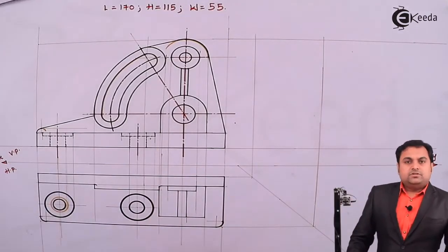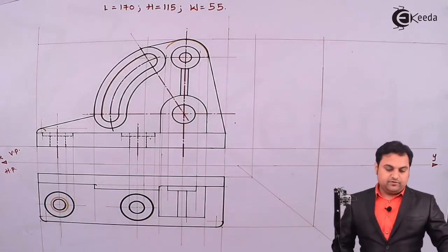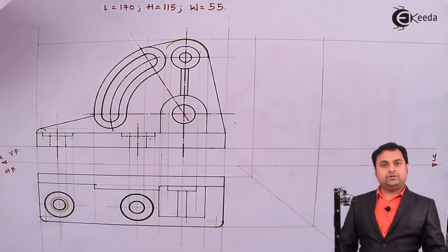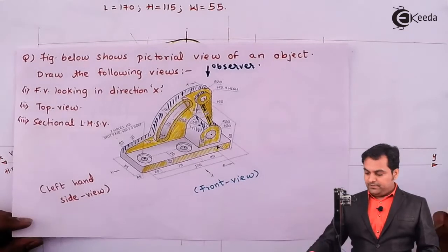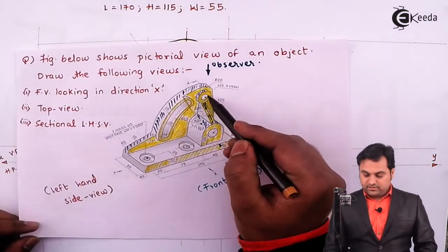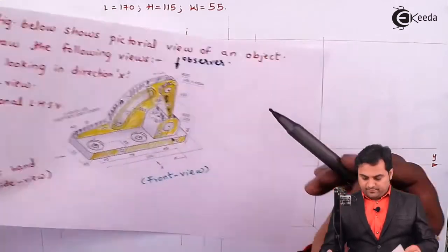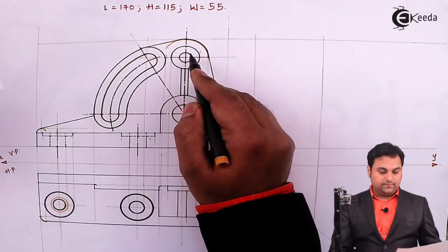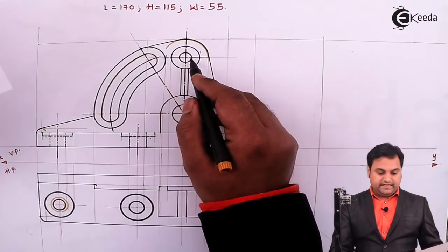So these circles, which are the spot face, are visible from the top view. Then I can say that this much is the visible portion in the top view. Now going for the hidden part, when we are looking from top, in that case there is a circle of diameter 25 mm. Inside this block or this circle, that is of diameter 10 mm.